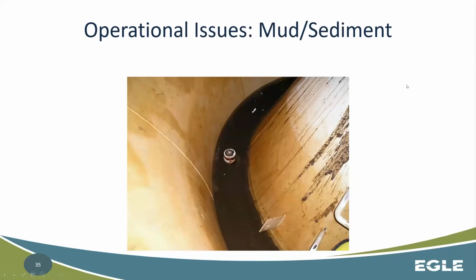So operational issues, mud and sediment. As water sits there, especially if your system is known for having sediment in your wells or high iron or manganese, those things can settle out or oxidize as it sits there, and then you're going to have some accumulation. Now you can see this little mud valve here, but it might not always get that.